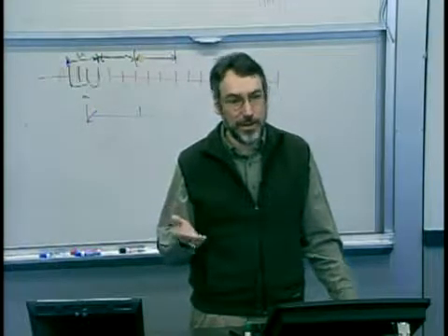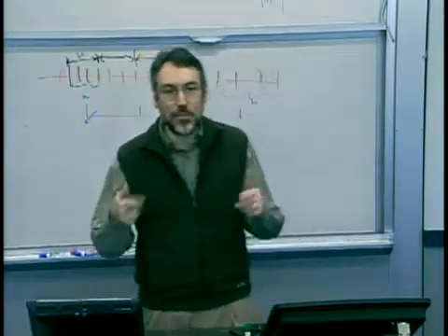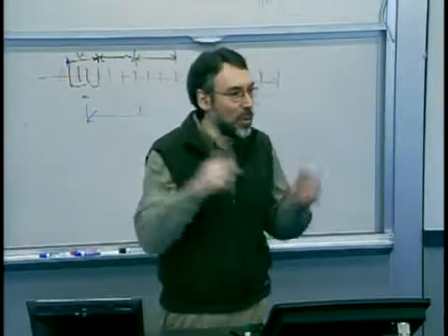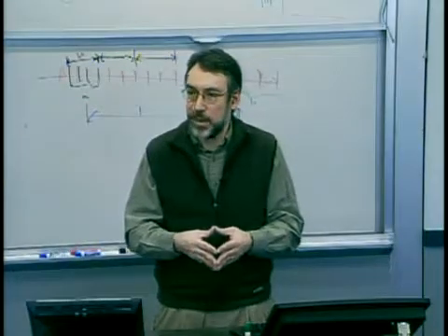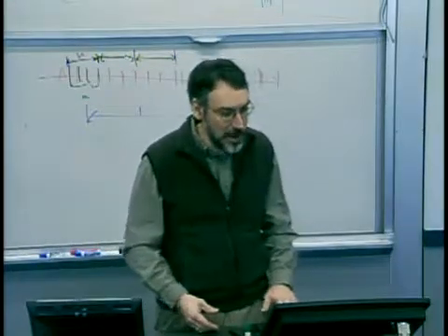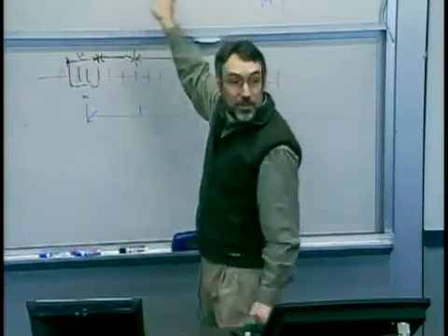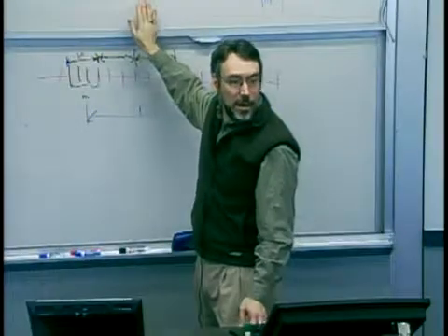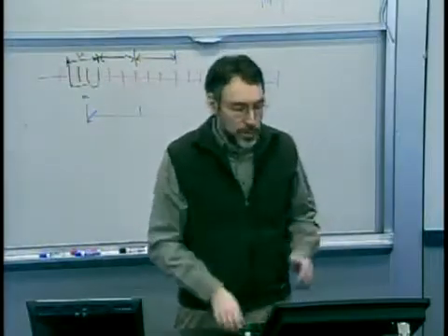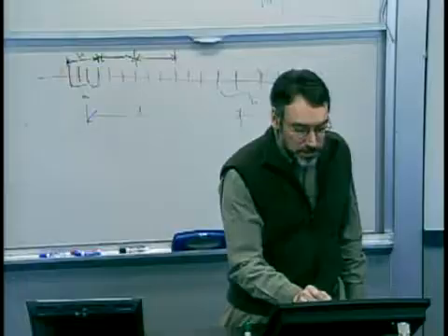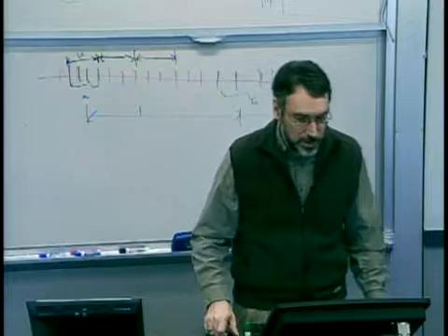Is the mean where we want it? Is the variance where we want it? Right? And in particular, how good is it with respect to our requirements for manufacturing a particular part or product? Okay? This is the notion of process capability. And what this also pulls in, unlike all of this, which is just probabilities on a normally operating or a not normally operating process, is for the first time the notion of design specifications. Different than control limits, okay?